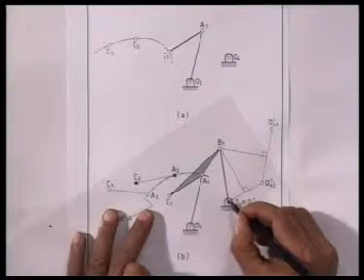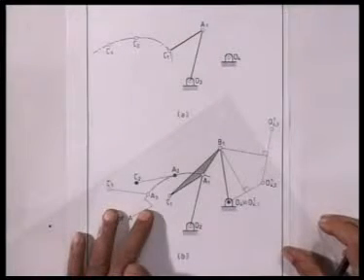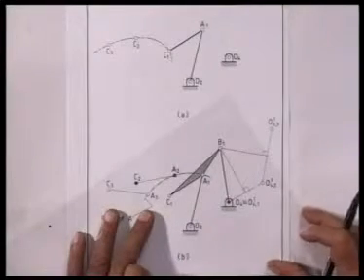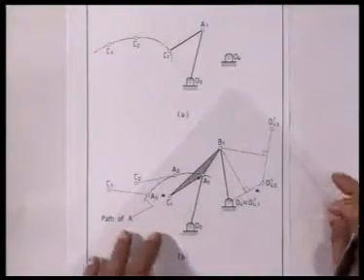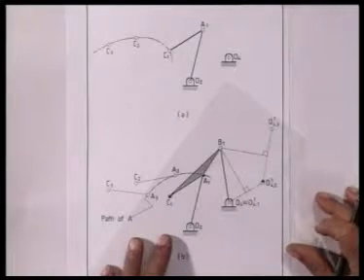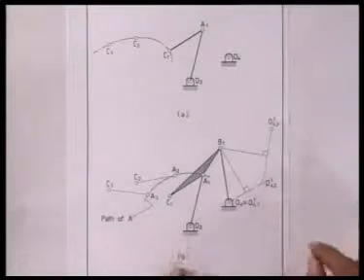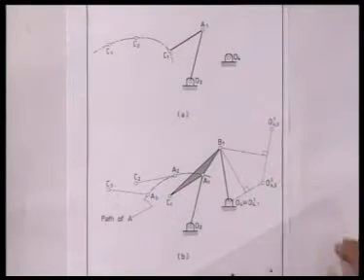These are the relative positions of these 3 points in the second configuration. So, if I hold the coupler fixed at its first configuration, that is A2 coincides with A1 and C2 coincides with C1, and wherever O4 goes, that I mark as O421.